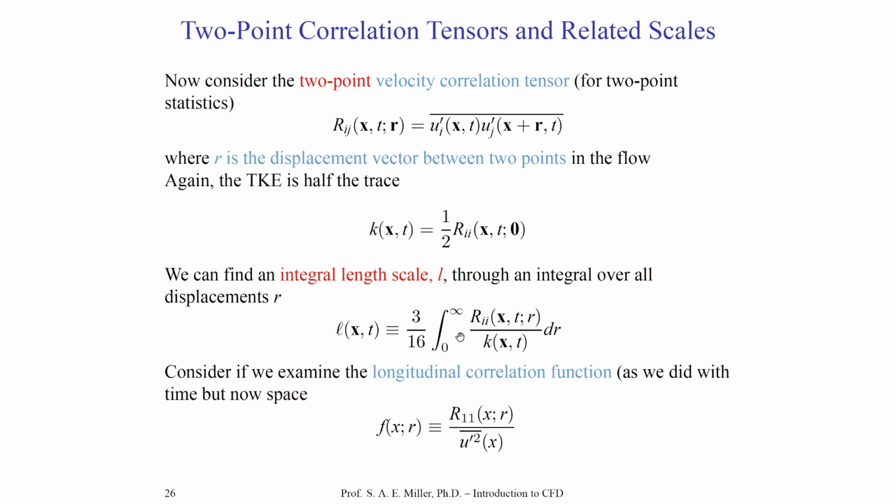Of course, we don't do this in practice because we can't evaluate an infinite distance numerically. But in practice, we can just go to a very large value because, by definition and statistically, because of the statistics of turbulence, we'll never find this value going to infinity over large distances. This integral will result, of course, in a length scale. That's the integral scale of turbulence, the largest scale of turbulence. And so now we've defined a time scale and length scale for integral scales.